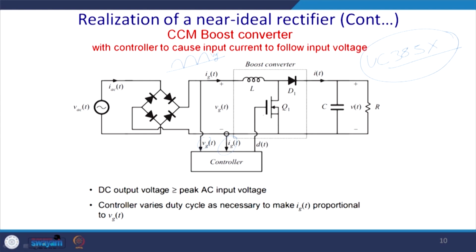Then accordingly the duty cycle of these MOSFETs is calculated, but please note that the MOSFET should have a body diode. Another issue is that for higher power ratings we require IGBT, and generally, as you know, it is a single phase application. So, it can be up to 3 kilowatt.